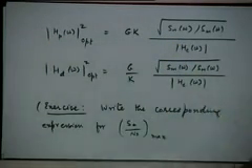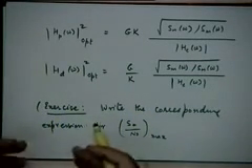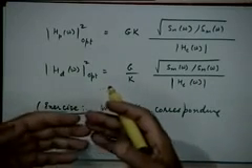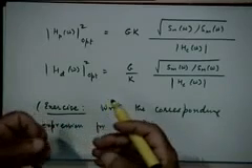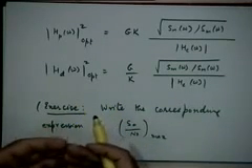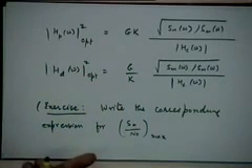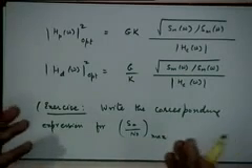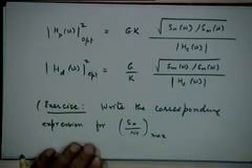Remember, noise is going to be added later in the channel, pre-emphasis being done at the transmitter. So knowing that the noise has certain distribution at certain frequencies which is significantly high, I must prepare the signal, ready the signal to take care of that. I must enhance the signal at those frequencies where I can expect the noise to be large, so that I don't have a poor signal to noise ratio even in that situation.